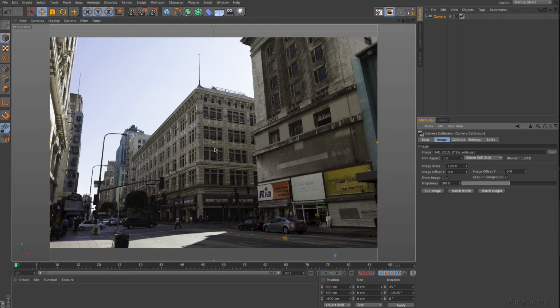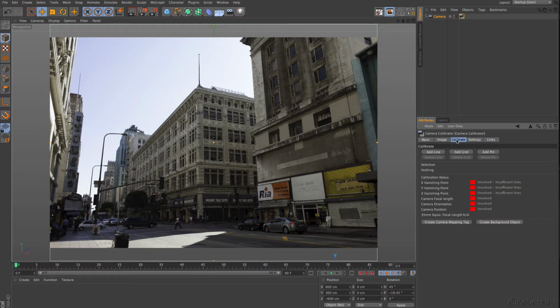If you know that you need an offset, that's fine. Normally, my suggestion, leave it at 0. Have the image full size, no crop whatsoever. It's the best idea because any camera looks always exactly to this middle point in the frame here when we talk about standard lenses. So with these settings all perfectly arranged, we can go to the Calibrate tab.